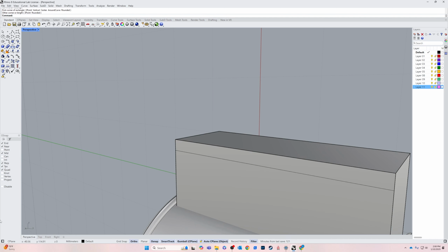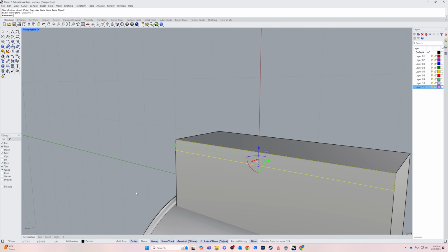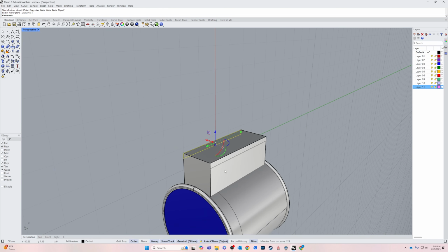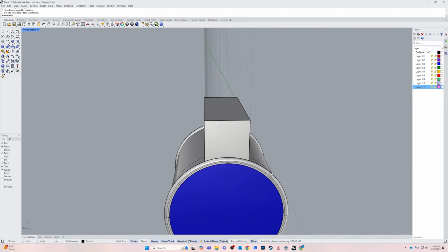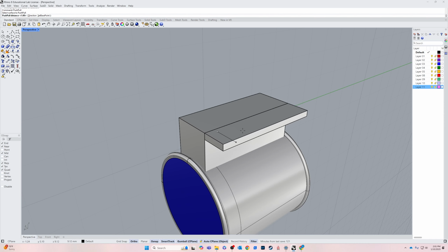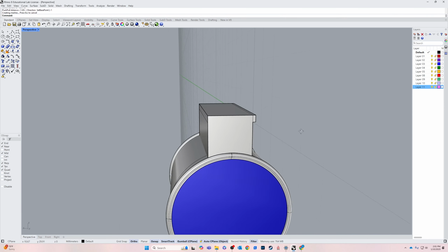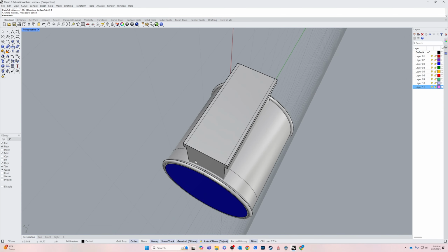Okay. And then I want to do a mirror of that. So I'm going to click on this, go to a top view, and mirror it so it goes onto the other side. So mid, and then draw the mirror line straight up and click. So now you should have, if you follow that mirror command, one on this side and one on this side. Okay. So let's do a new command, push pull. This is one that's brand new for Rhino. Click on this, and I'll do 1 millimeter this way and 1 millimeter that way. Okay.